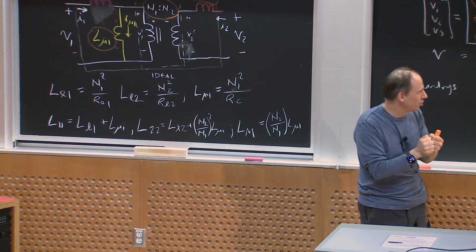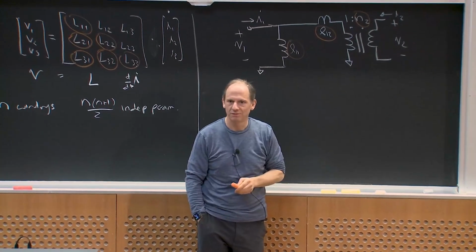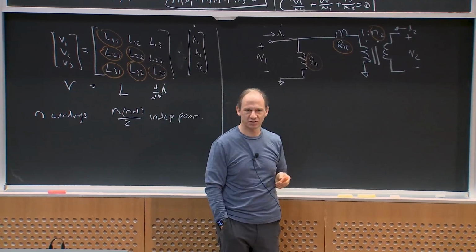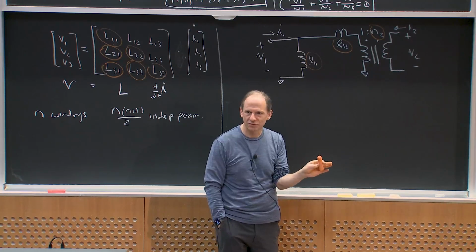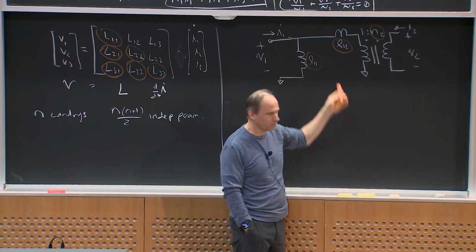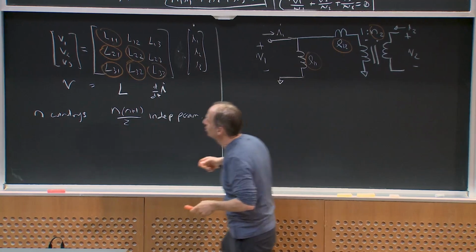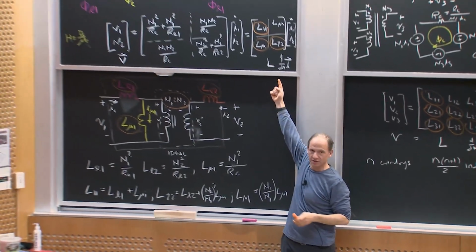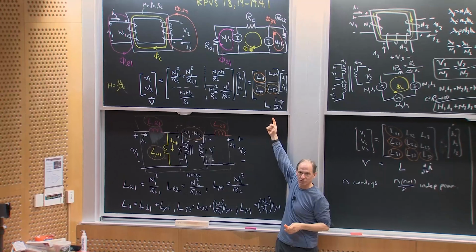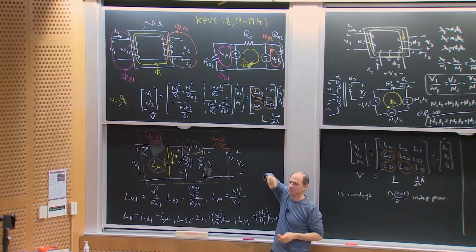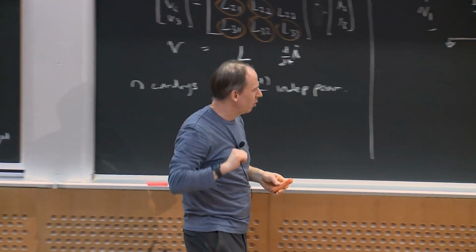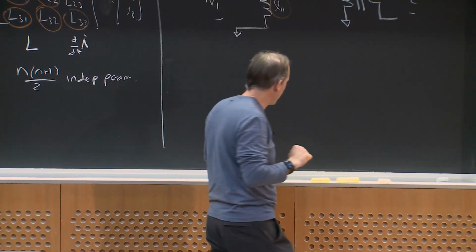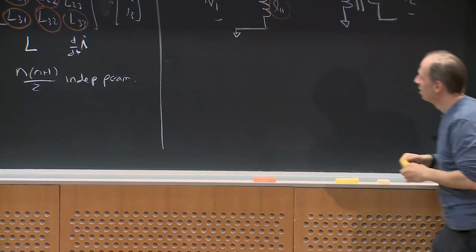Okay? So you can easily get some negative inductance value in your model if you're not using a physical model. All right? And so don't get concerned if you see that. That's just because you're trying to pick parameters to really match what the inductance matrix description does. Whatever those circuit parameters turn out to be, you'll get the right inductance matrix description. Okay, so this is great for a 2-winding transformer.